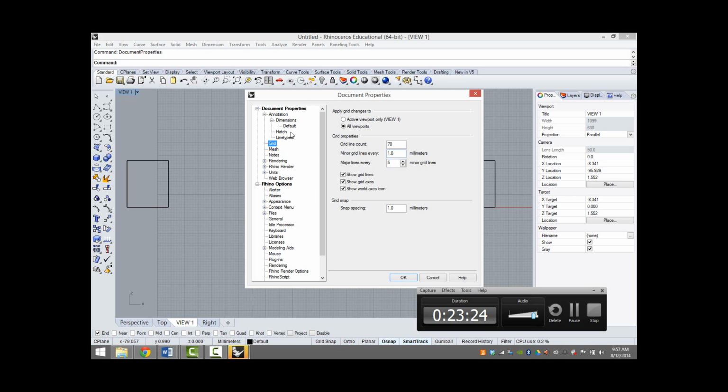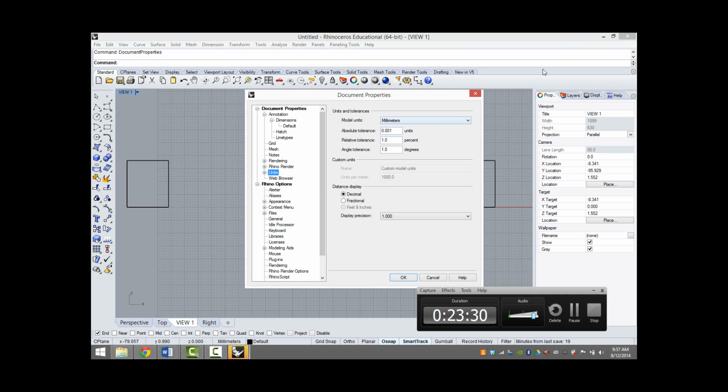How did that happen? I thought I chose large objects, inches. Let's change. So we'll go into units to change that. So if you find yourself in a millimeters document, you can select units and then drag down to inches and then feet in inches. And for most of the work I do, an eighth of an inch precision works. Okay?